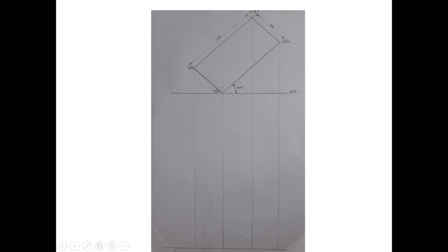From the bottom of your drawing sheet, just provide 1 centimeter. Draw this line 1 centimeter above the base bottom. Then you drop all the points to that line. So EFGH and ABCD and EFGH to that line, you will get some points here. Then you can draw the